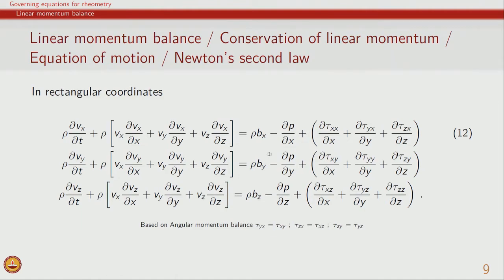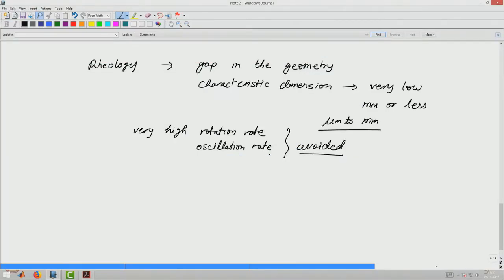So, based on these different terms, which are basically related to force balance, we can try to analyze a given rheometric flow. We can begin with a simple example that we have seen many times, the case of parallel plate flow, where we have the coordinate system y and x, and the top plate is moving with a certain velocity. Of course, instinctively we have been drawing the overall velocity profile which is linear.